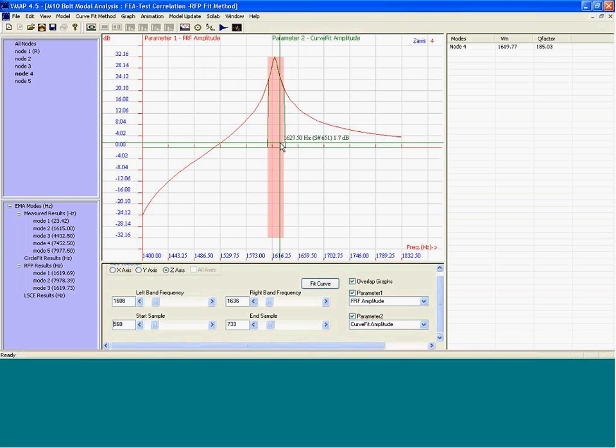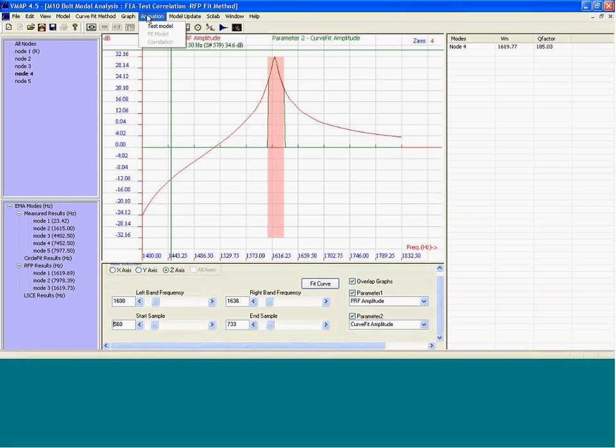data. And the reason this is done is once the curve fitting is performed, you get a parameterized function where the parameters are the modal parameters, which are resonance frequency, Q factor, and mode shape. I've shown the extraction of resonance frequency and Q factor. In a short while, I'm going to show the mode shape as well.